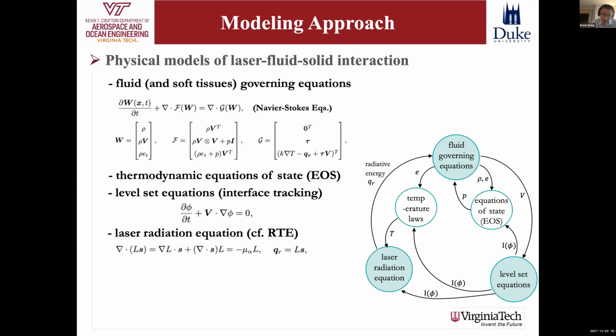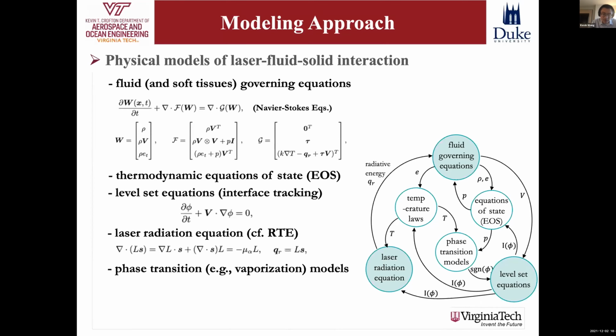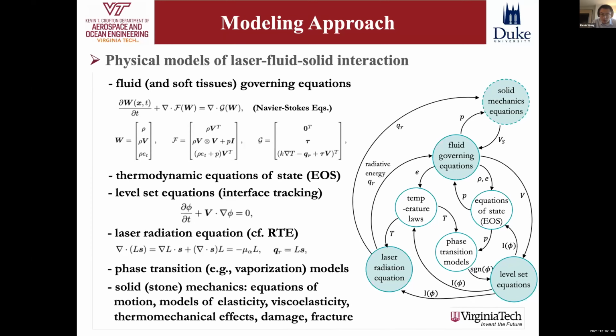We solve the laser radiation equation, which is a simplified form of the general radiative transfer equation, or RTE. To account for the effects of cavitation bubble dynamics, we need phase transition models, particularly a vaporization model. And finally, we need to solve solid mechanics equations to get the displacement, deformation, stress, damage, and fracture in the kidney stone. Now, if you look at these equations or models, the solution for each one of them is not new. However, the solution of the combination of these equations as one system is relatively new